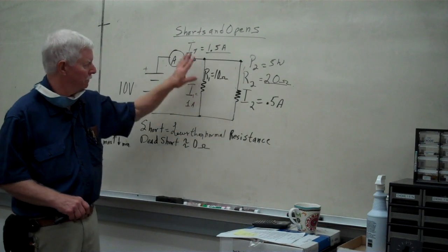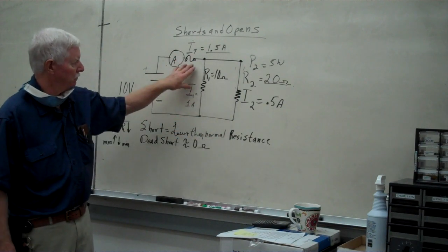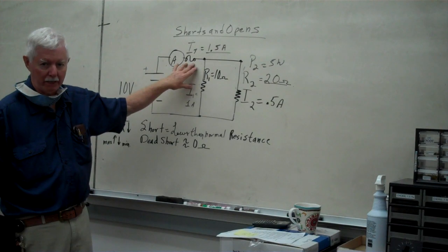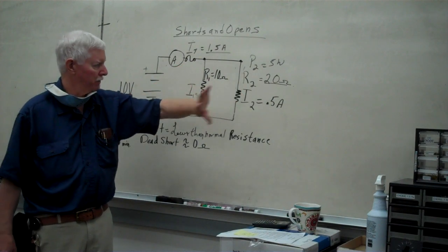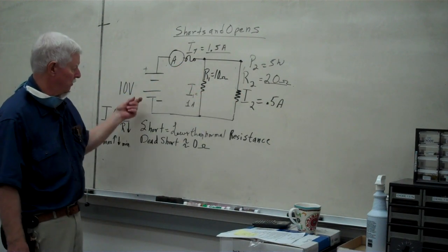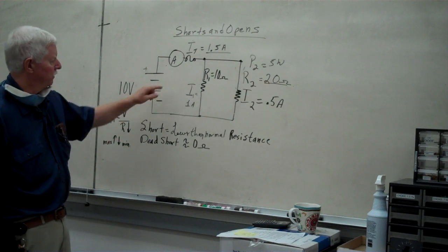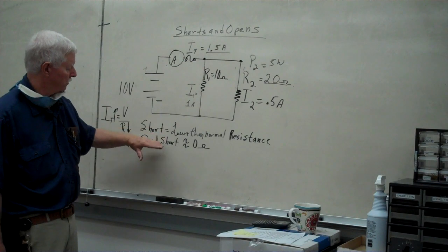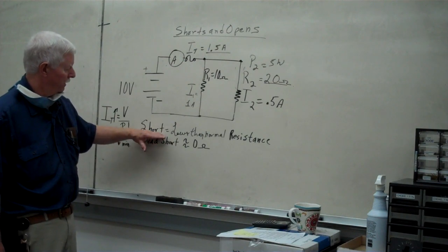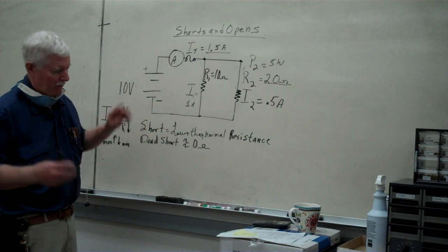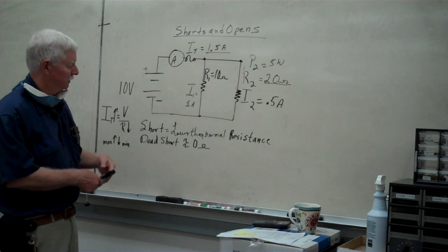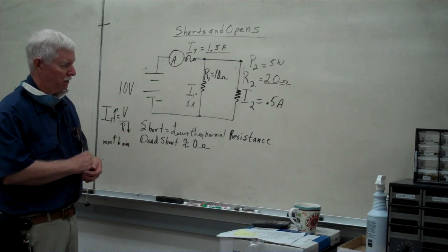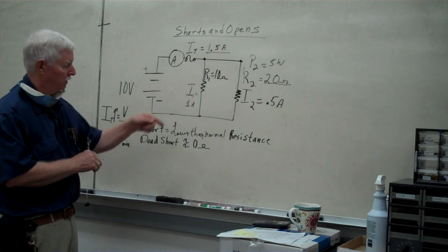Lower than normal, it may come on for a while. Hopefully the fuse will warm up and break in that time before any other damage could happen to the rest of the circuit or the power supply. But there is a jump in the current when you do have shorts occurring. Dead short, really bad shorts. It could be just lower than normal resistance, could be just a little bit higher than normal current going through that particular part of the circuit.